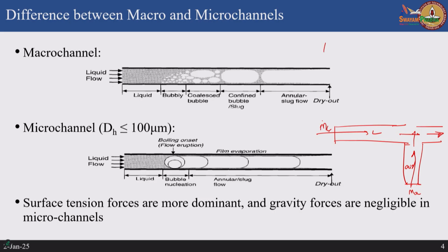One is called the adiabatic two phase flow pattern. These flow patterns are produced by mixing say air and water in a T junction, and looking at the different mass flow rates of air for a fixed mass flow rate of the liquid, and by changing the ratio of the air flow rate to the liquid flow rate, I can look at different flow patterns that are emerging.